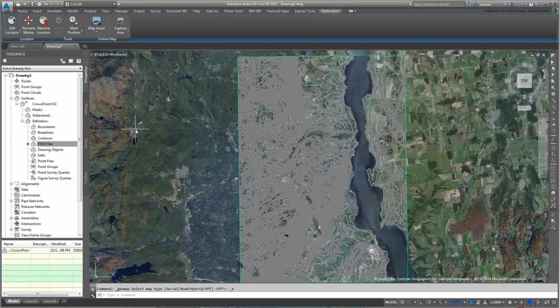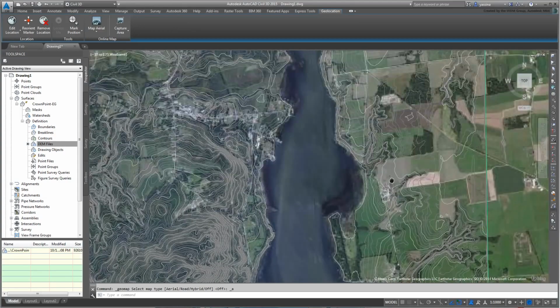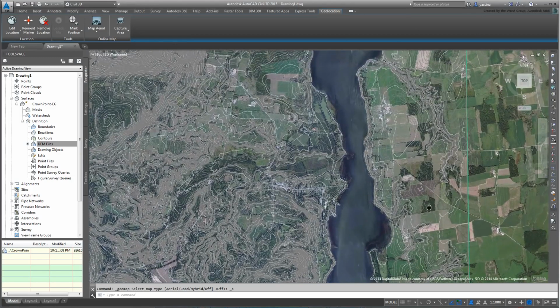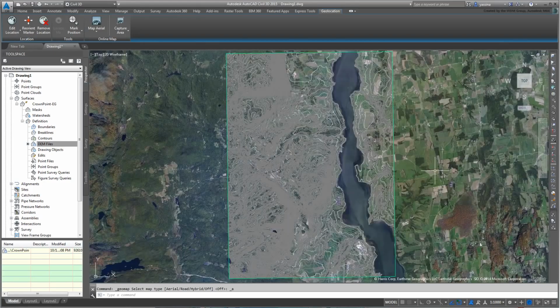The created surface is quite detailed and somewhat too big for your needs. You only need a small part around the water crossing area. In fact, you need to define the same area you used earlier to create your ground texture map. Instead of fiddling with the original surface, you'll make a copy and trim that copy to the area of interest. That will also enable you to bring down the level of detail on the copy, while the original surface retains its resolution. Start by hiding the original surface.